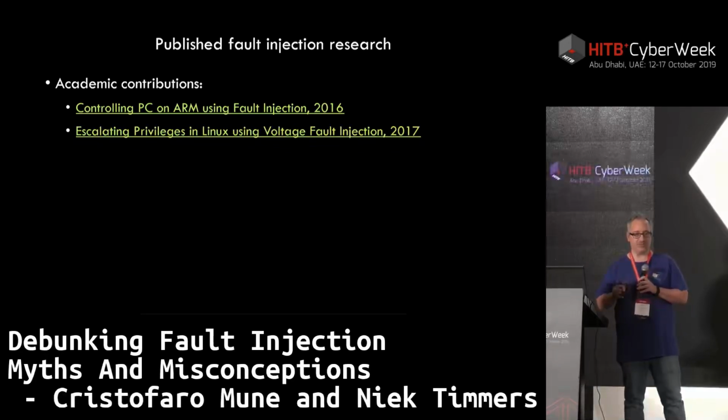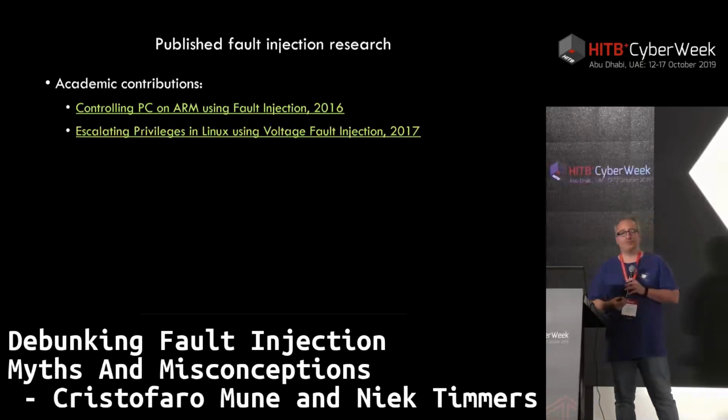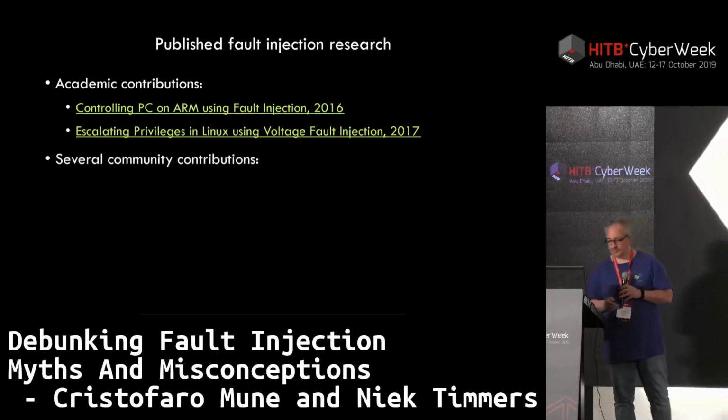So it's not a matter anymore of what you can do with actually random faults, but precise control of the program counter. And we used this technique in 2017, which has been presented at several conferences, in order to escalate privilege from user space Linux to get control of the kernel with a program counter, using voltage fault injection and without the need of any software vulnerabilities, just by using that.